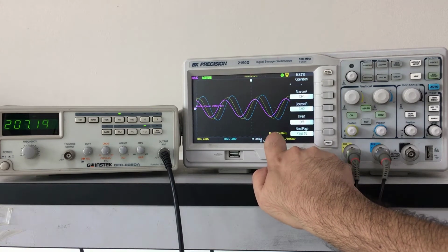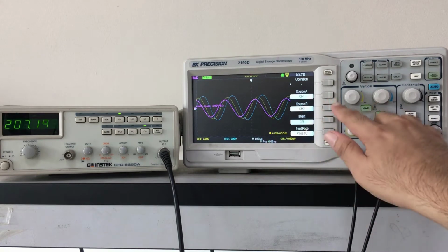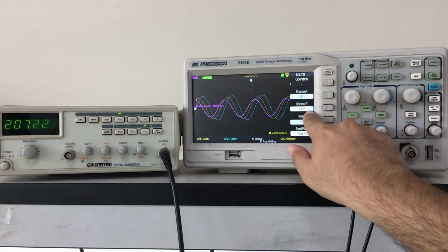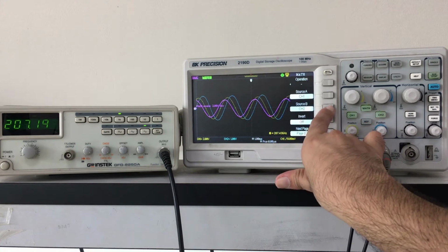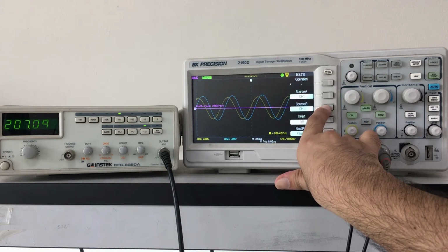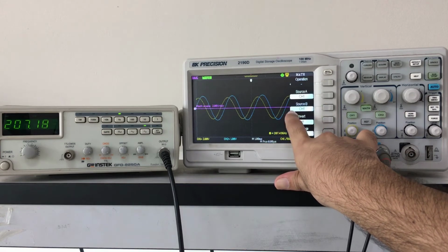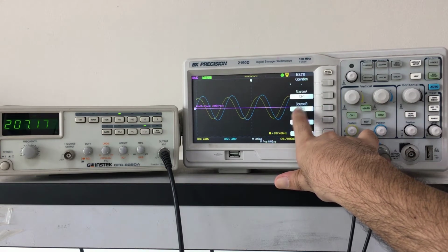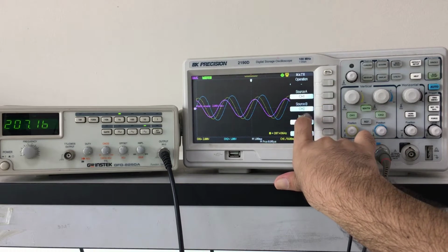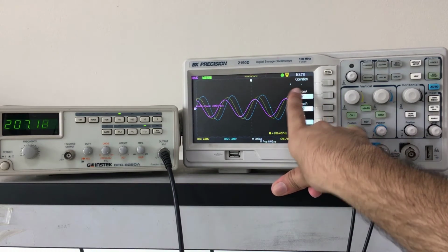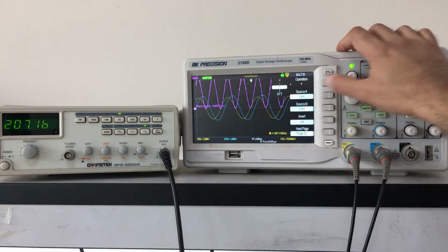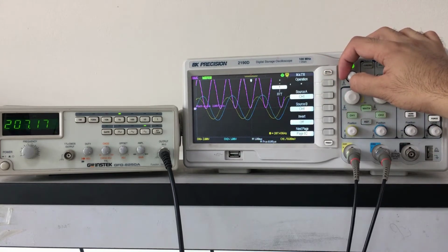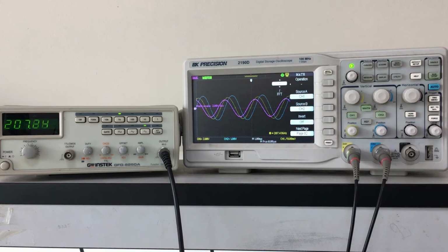If you need to change any settings, you can easily do that by pressing the button corresponding to each of the options. So if you need to change a channel in the source, you can just press the corresponding button. If I press this button, this became channel 1. If I need channel 2, I can just press this button. The operation is minus. If you need to change the operation, just press this button and you will get a lot of different operators. We will keep it at subtraction because we need to perform a subtraction.